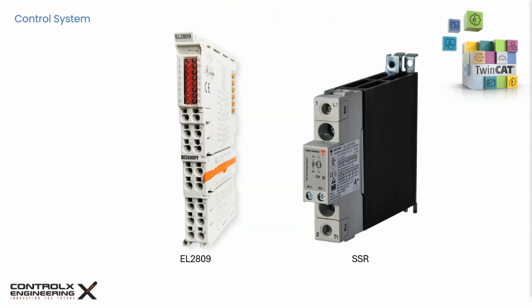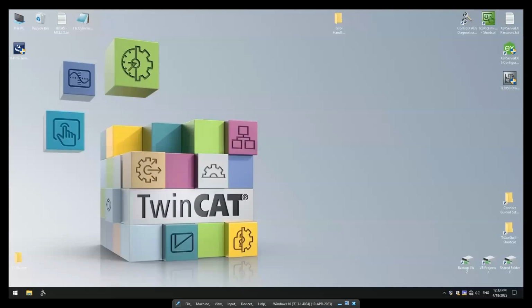For the SSR control, we will use Beckhoff's EL2809 digital output terminal. It has 16 channels and uses 24-volt logic level, which is suitable for my chosen SSR. A single terminal can control up to 16 heaters independently. With typical switching times in the range of microseconds, it is fast and suitable for PWM control. Now that we have covered the hardware side of things, let's hand over to Andrew, who will go over the TwinCAT coding side of things. Hello everyone, this is Andrew, and today I'll be walking you through the implementation of TwinCAT's temperature controller function. Let's begin.